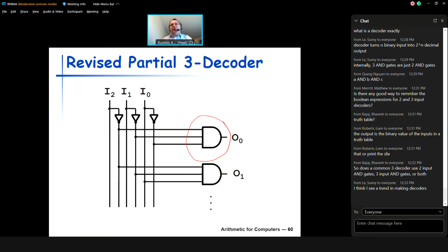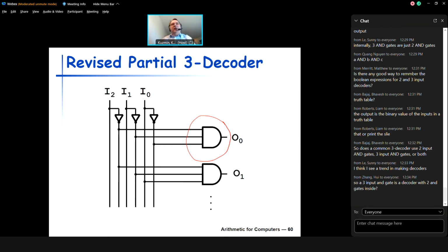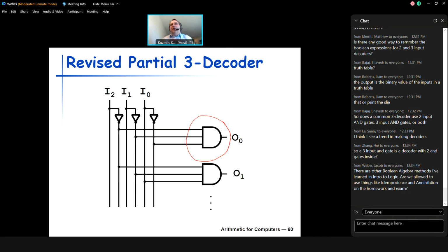But if you're using any of those programmable devices, usually you have a grid of input signals that you can connect pretty much arbitrarily, and that essentially gives you the ability to have gates with as many inputs as you have input signals. So if you have 200 inputs, you can have an AND gate with 200 inputs, so that you can combine all your input pins with a single AND gate if you need to.